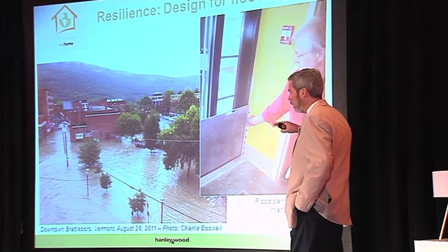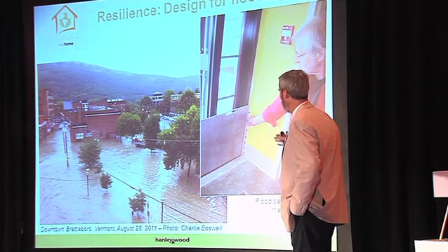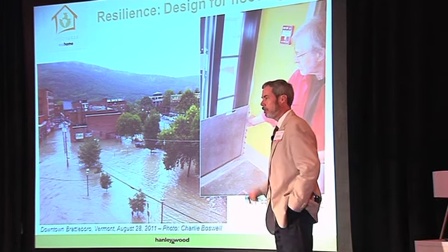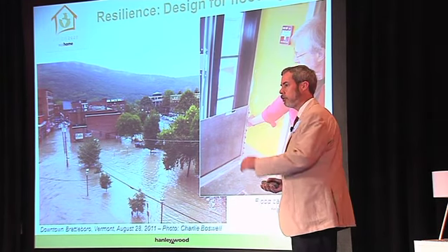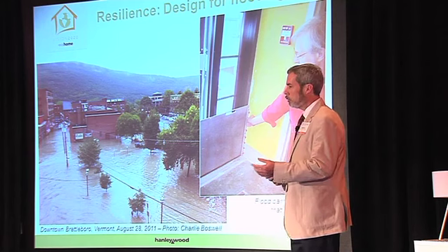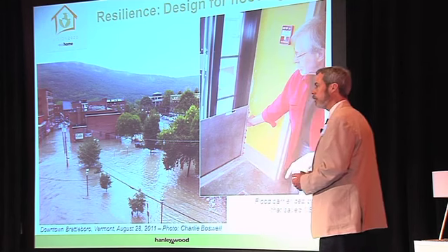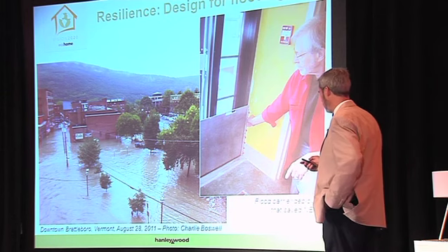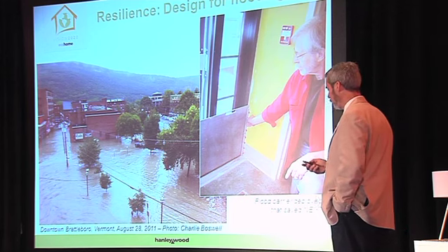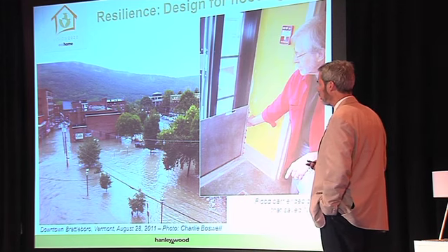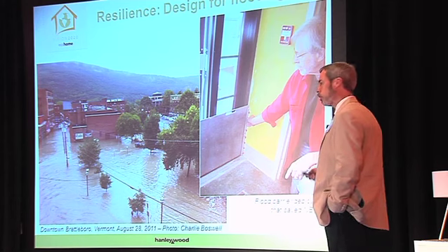And in engineering it, even though the building was a foot above the 100-year flood level, they put in these flood barriers. And the last person that left that Sunday morning deployed those 18-inch flood barriers. The water came up to within 1.5 inches of the top of those, saving the building. There was very minor damage, a little bit of seepage, but a great example of a great product that's very cost-effective, inexpensive, and easy to value engineer out of a project, but important to keep in.